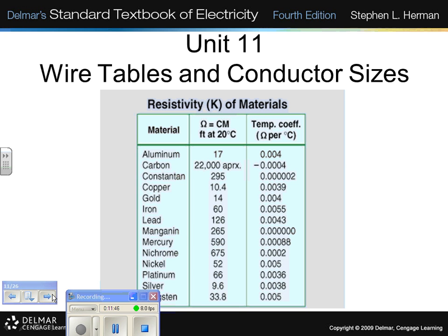Now, Mike Holt, so I took his number and I flipped it around and go, what the hell is he talking about? And guess what it is? 60 degrees centigrade, that equipment terminal temperature, which makes absolutely no sense, because the tables are set up for 30 degrees ambient temperature, not 60 degree terminal temperature. And if you're confused by that, don't worry about it. It's just that Mike Holt, I don't think, realized that he had confused two ideas, but that's a whole different opera.